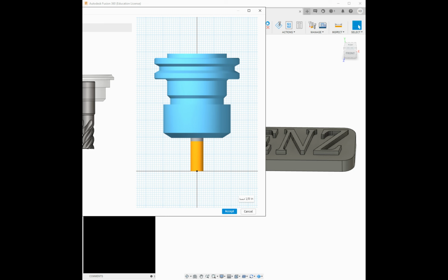Pretty much all of our mills are going to be clockwise. Our number of flutes, we can just count that. So what you want to do is either have the specs of the end mill that you're programming, or have the end mill in front of you so you can take a micrometer or caliper and actually measure these things. Or in the case of flutes, aka teeth, you just count it. We're going to be using a lot of 2 flute end mills on wood. We could use a 1, you never know. Material is going to generally be HSS or carbide. Most of the beginner stuff we're going to do is high-speed steel, because it's much cheaper if you break it.